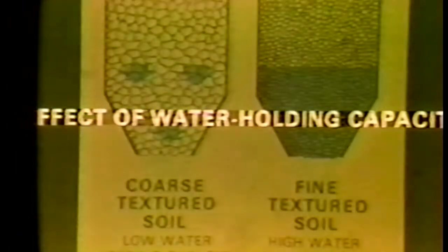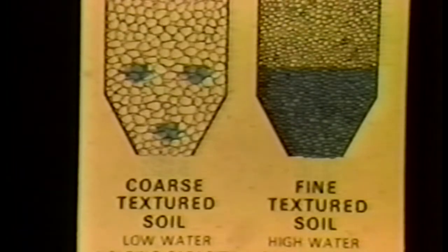The water holding capacity of the soil must also be considered. The water holding capacity of soil is the amount of water it will hold after the free water has been drained away by gravity. Soil texture affects water holding capacity even more than it affects water intake rate.